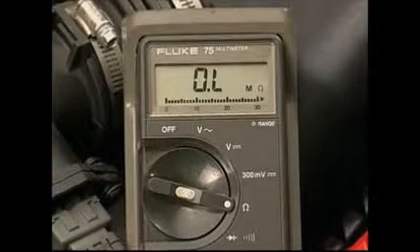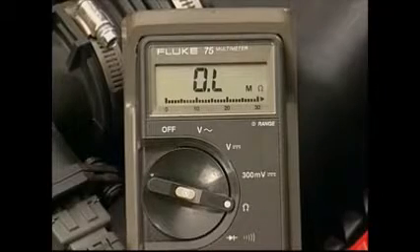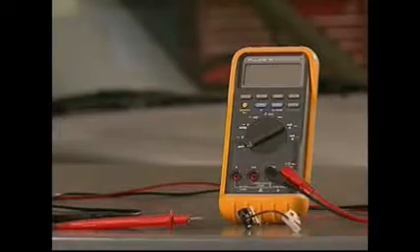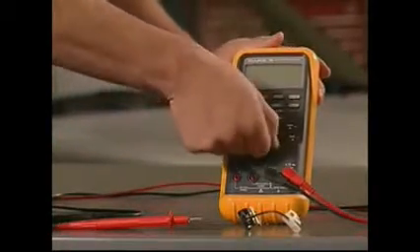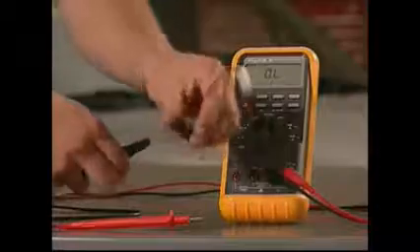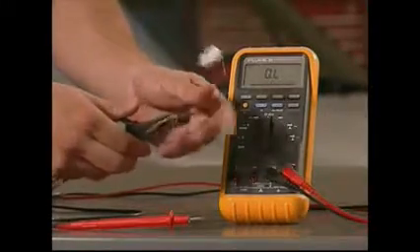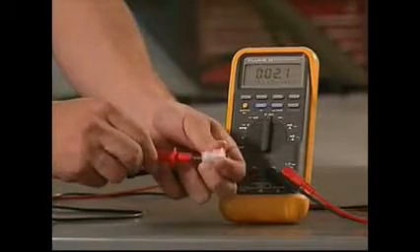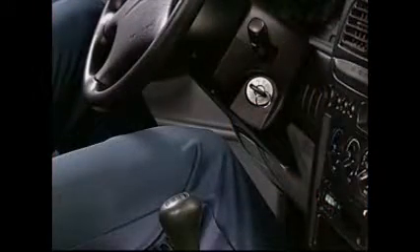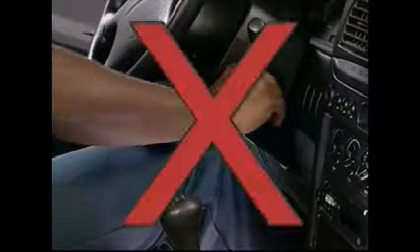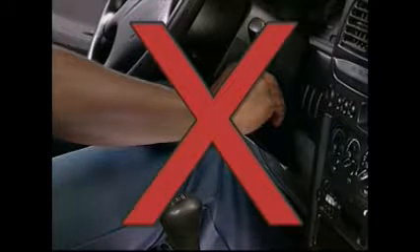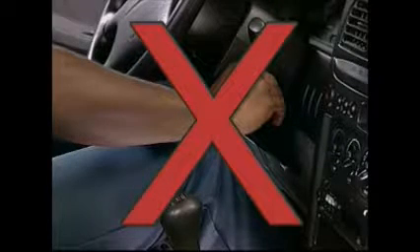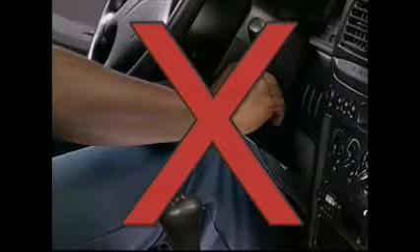Resistance in a circuit is measured in ohms using the ohm meter function of the digital multimeter. On the Fluke 88 digital multimeter, you can select the ohm meter function by turning the rotary selector to the ohm symbol. The leads of the ohm meter are connected to the same ports on the meter as are used for the voltage tests. The critical difference in using an ohm meter is that there must never be voltage present or current flowing in the circuit when you are using an ohm meter. The use of an ohm meter on a live circuit will damage the meter.